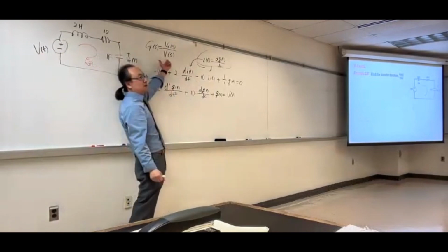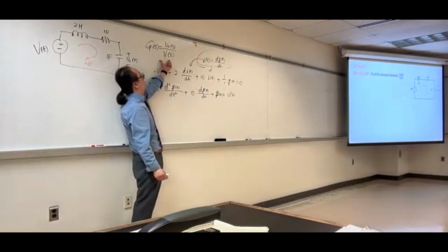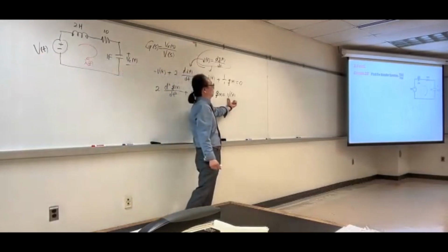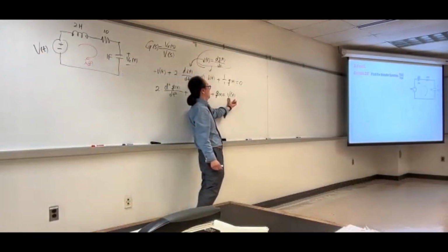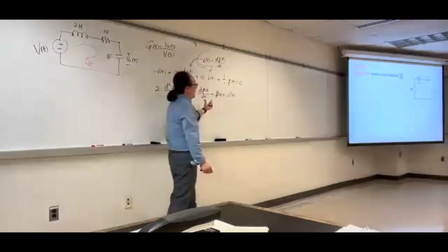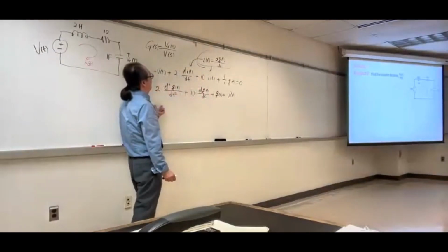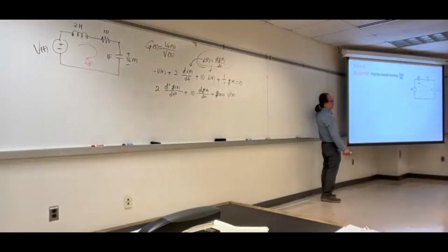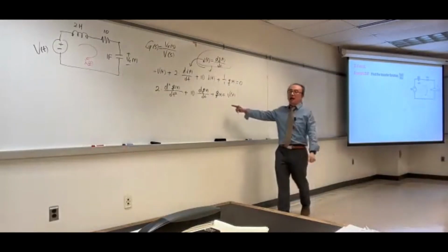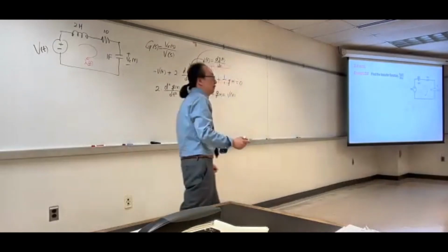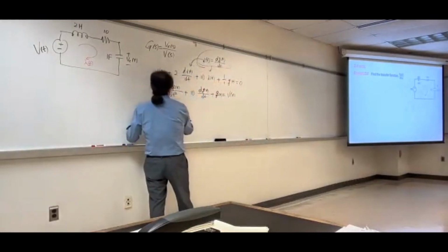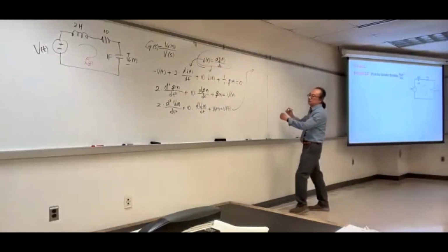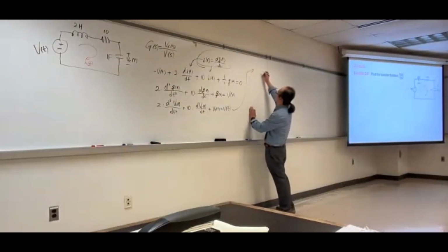The transfer function that we need to find is given as VC of s over V of s. We have a v of t, and when you take the Laplace transform of v of t, it's going to be V of s. However, we don't see any VC of s. However, we have this relationship. Therefore, anywhere you see q of t, we can simply replace it with vC of t. Then take the Laplace transform of that. All the initial conditions are 0.